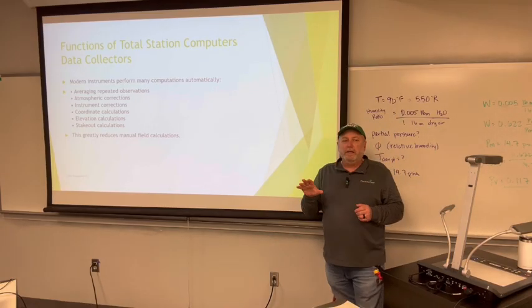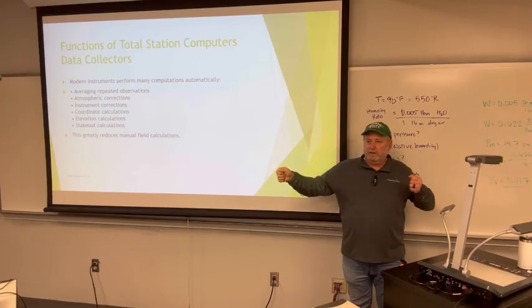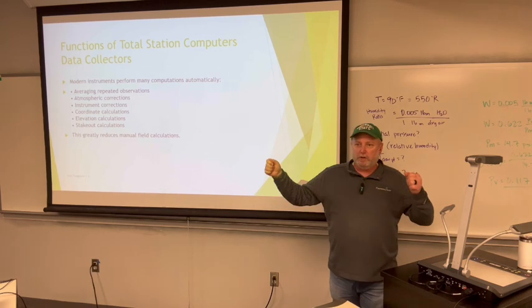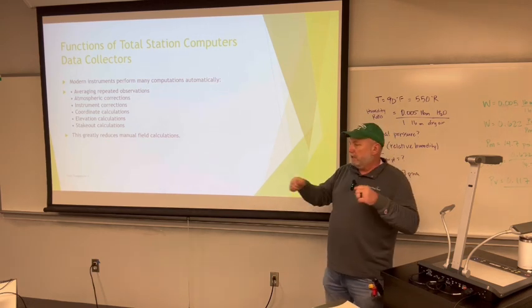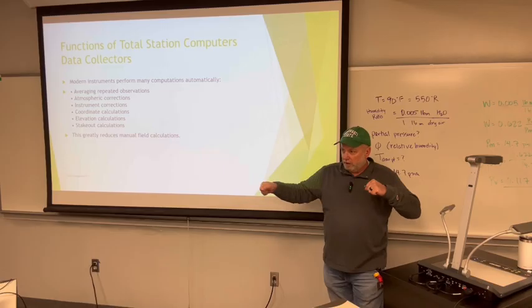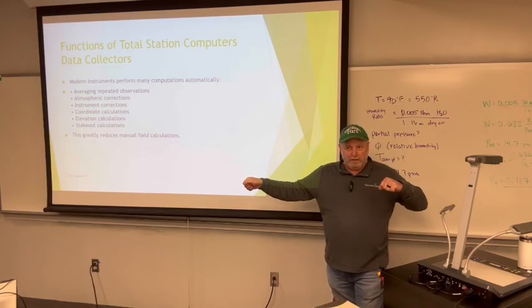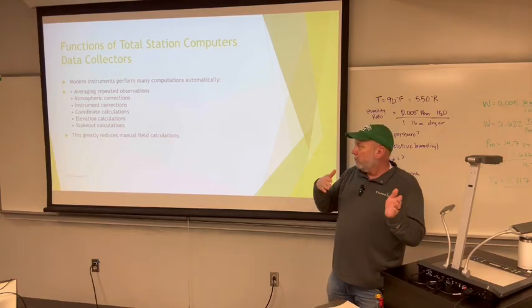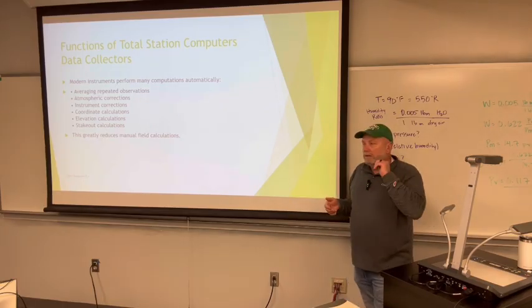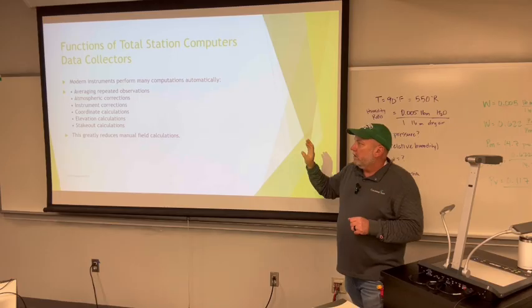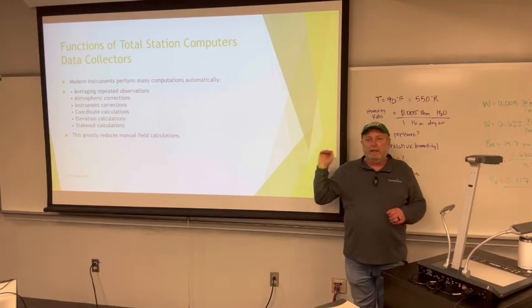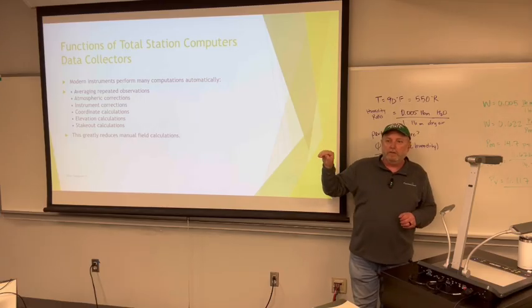We talked briefly in the horizontal distance lab, like the steel tape, you have calculations for sag and temperature and things of that nature. The temperature has to do with the coefficient of steel's expansion and temperature. It can expand, contract, depending on how warm or cold it is from the standard. Those kind of things also have an effect with the laser that these instruments shoot out.